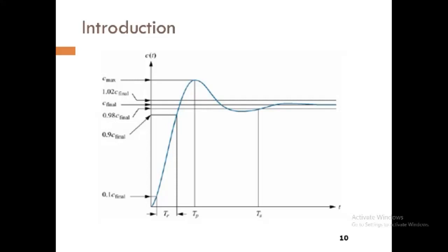When a transient occurs, the current and voltage in some part of the circuit may many times exceed those in the normal behavior and may destroy the circuit equipment in its proper operation. During the transient, all the quantities such as current, voltage, power, and energy change in time, while in steady state they remain invariant, that is constant in DC operation or periodic, having constant amplitude and phase angle.